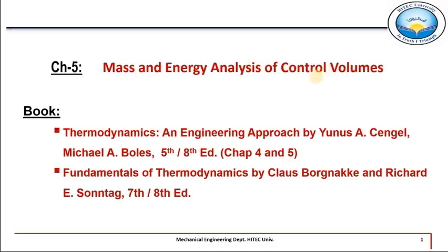Control volume simply means the open system in which mass is entering and mass is also leaving. That's why it is not just energy analysis. You can see here the term mass is also written, because now we are discussing the control volume. So it is mass and energy analysis of control volumes, because mass is not fixed within the system boundary. Mass may enter and may leave the thermodynamic system boundary.